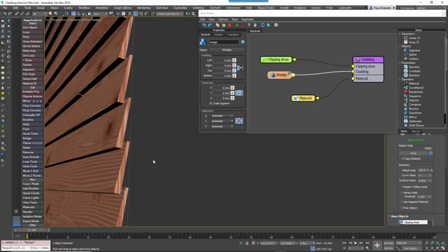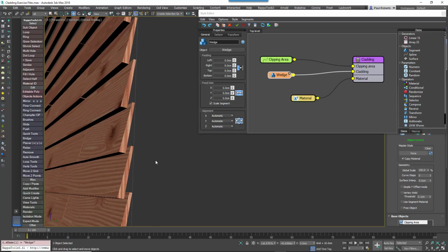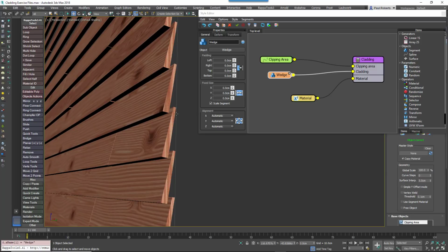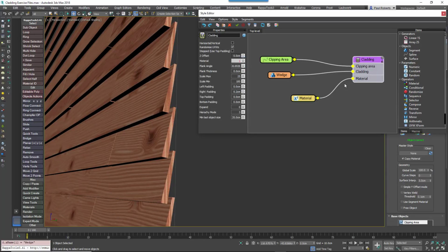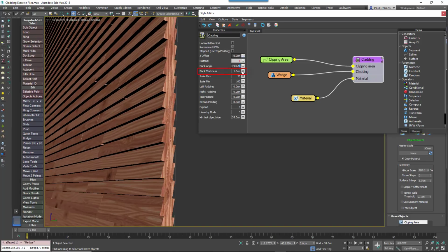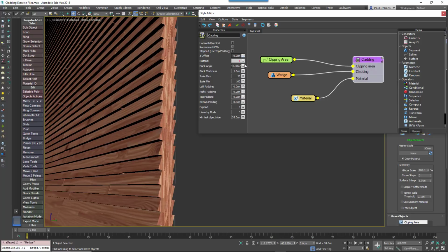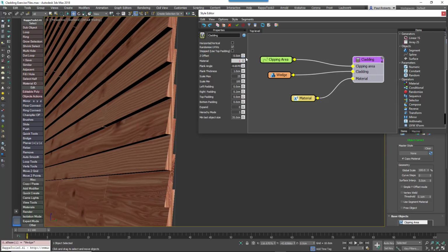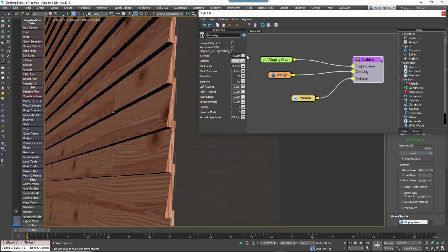If we swap the plank for this tapered style, we can see a limitation of the plank angle feature though. It uses the bounding box to calculate when the board should overlap. But because this is tapered, it's narrow at one end and it's calculating it slightly incorrectly. The thickness parameter is therefore used to override the size used internally to calculate this overlap. Enter the thickness here that's the size of the plank at the end you're wanting to overlap. In this case it's about 1 centimeter.